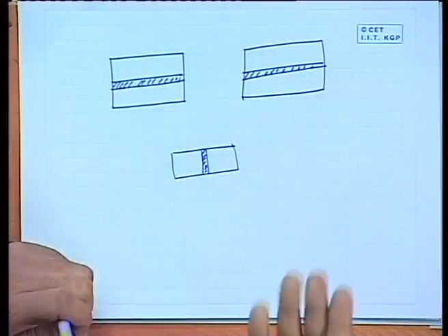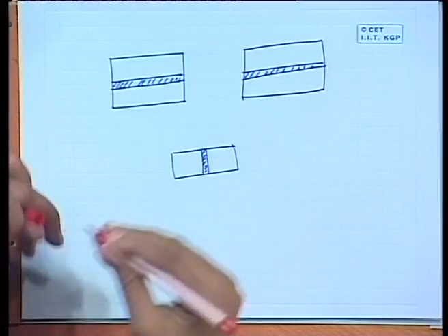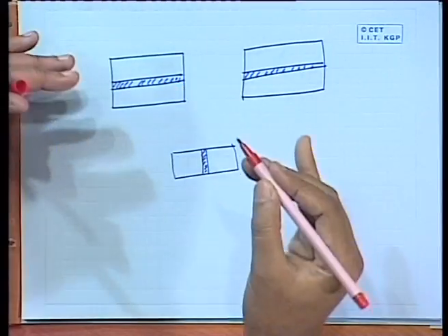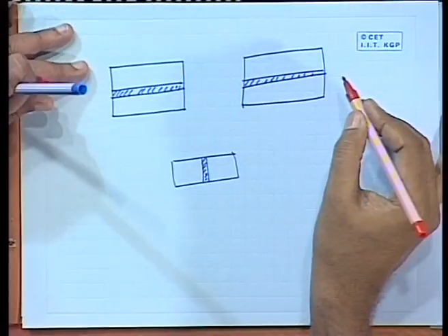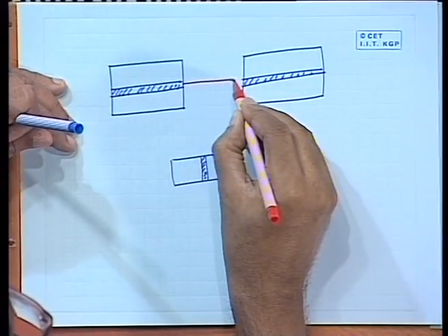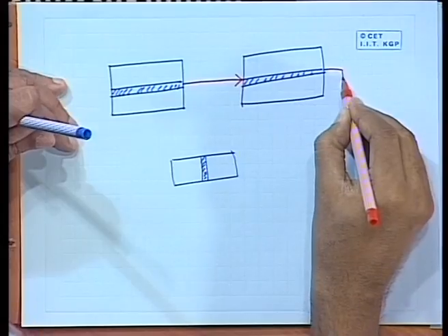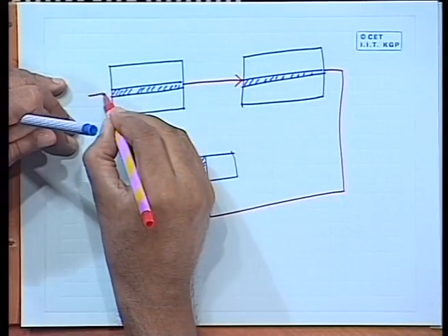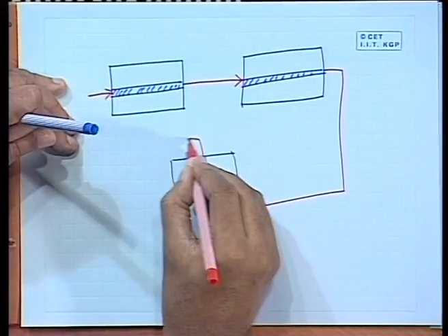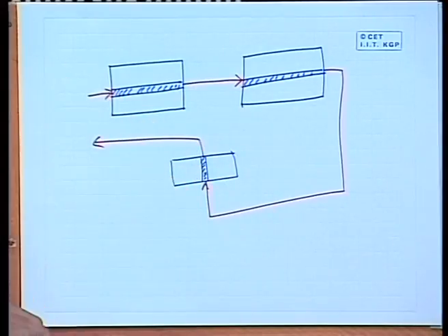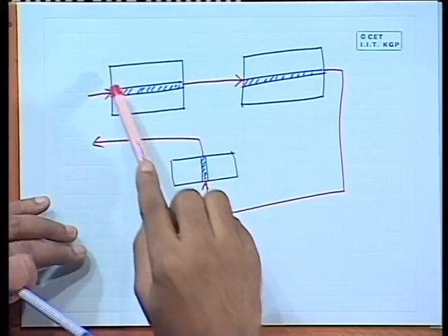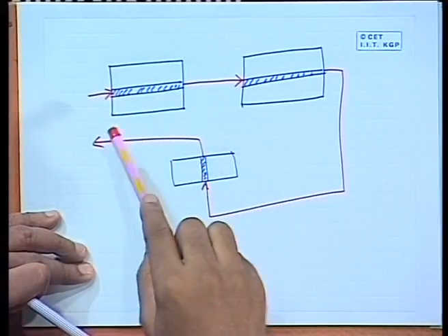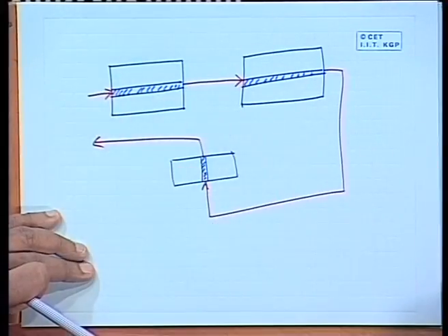Now, these modules you are developing hierarchically. Now, when you put all of them together on the surface of the silicon and try to interconnect them, you can also integrate the scan paths. So, now this will be your scan in and this will be your scan out. So, instead of considering the whole circuit together and doing it, you can do it individually.